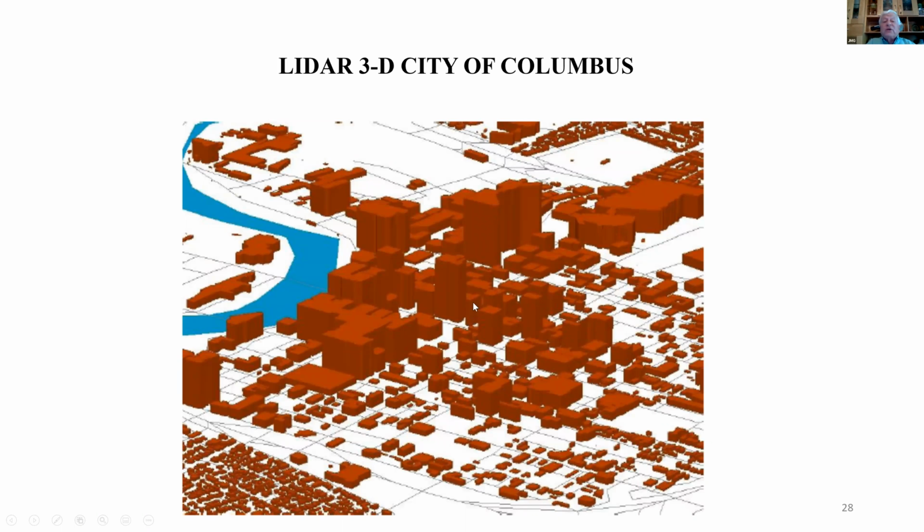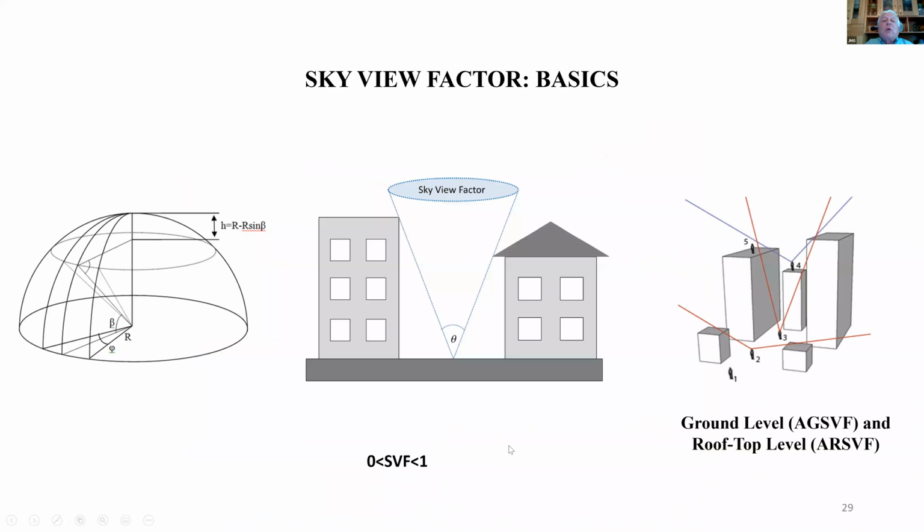That was a first piece of information that we had to do to compute a lot of variables. For instance, having the rooftop areas of all the buildings, but also morphology variables and solar insolation variables. I'm going to talk about that. One important piece of information is called the sky view factor. Here, you measure at the ground level how much of the sky you see. That can be computed, of course, with the computer; there are no hand calculations. If there is no obstruction to your view of the sky, you can see the sky in every direction. Let's say you are in the countryside in an agricultural field, the sky view factor is equal to 1. If it's nearly all covered and you can't see the sky, the sky view factor is 0. So it varies between 0 and 1.